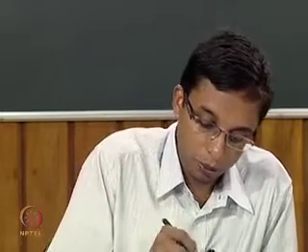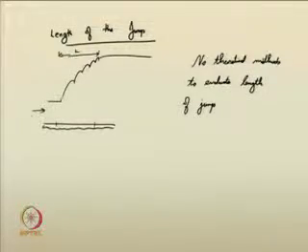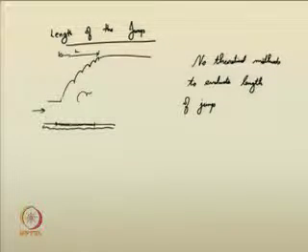Suppose high velocity water is coming here, it can scour the channel bed. You are now going to create a hydraulic jump to dissipate the energy, which we will be discussing later. But due to this high impact velocity, high jet flow, there could be scouring. So, for how much length you need to incorporate protection in the channel bed, for that also you need to understand the length of the jump. Up to this much region you can give a proper, better protection compared to the other regions. That way you can economize your channel beds.